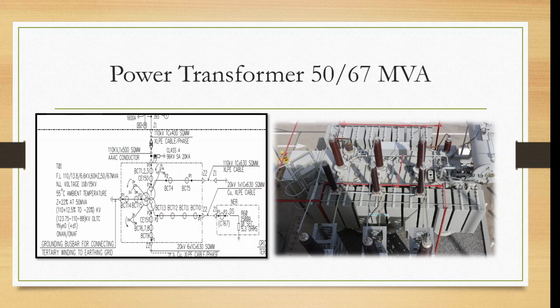It is an automatic device controlled locally from the transformer, and it can be controlled remotely from the SCADA system, from the control room, or from the HMI, the SAS. The new modern substation has a substation automation system which can also control functionalities like OLTC. In normal small transformers, these tap changers are actually off-load and can be operated manually, like in this substation, in the auxiliary transformer, the tap changer is manual.